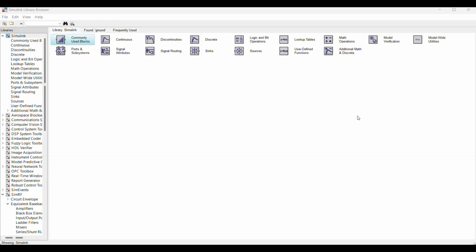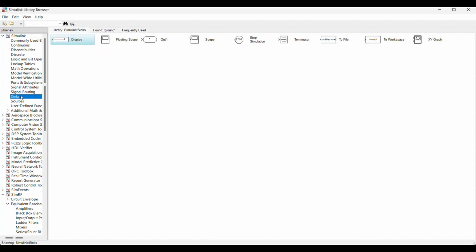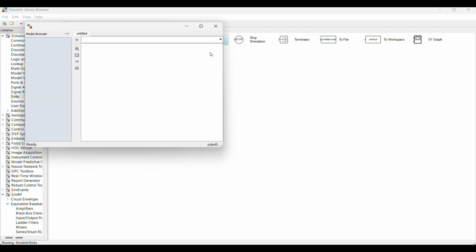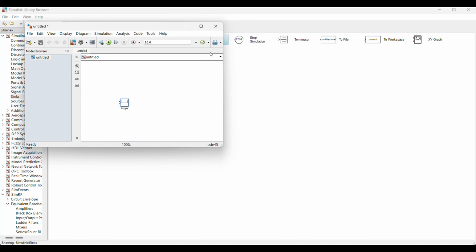To create a single phase full bridge inverter on Simulink, at first we open Simulink on MATLAB and go to libraries. After we go to libraries, we collect our necessary components and add on our blank model. So let's start with collecting the components. At first we go to sinks and add scope to our new model to check voltage measurements and get a voltage graph.